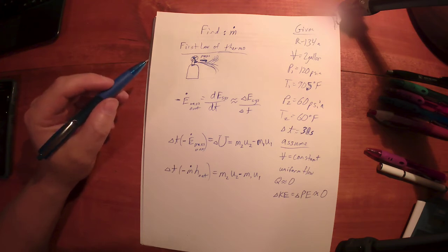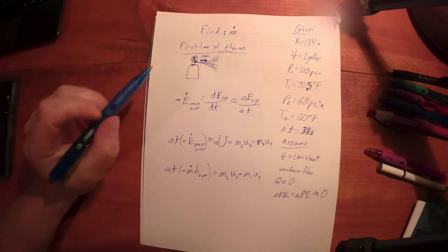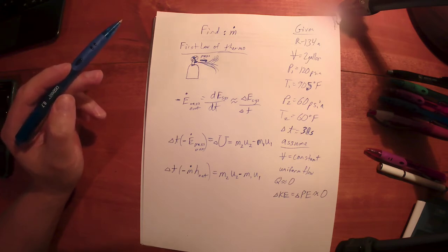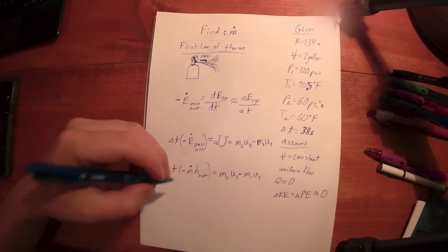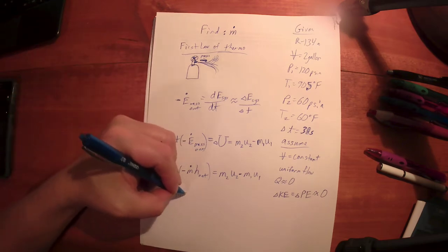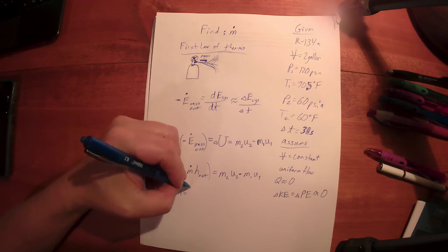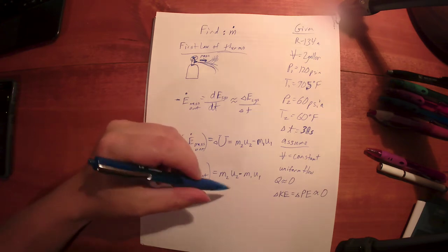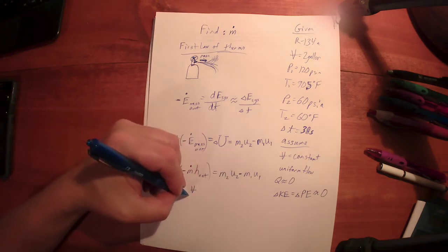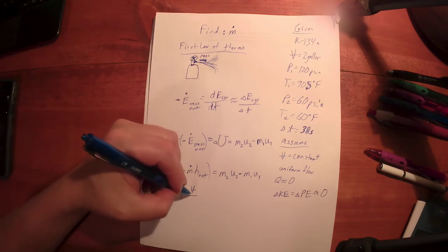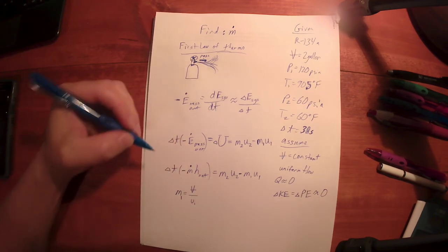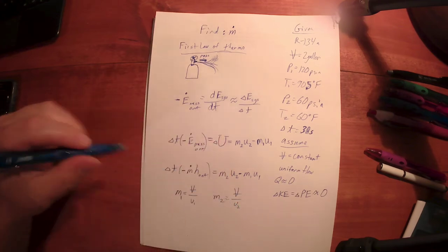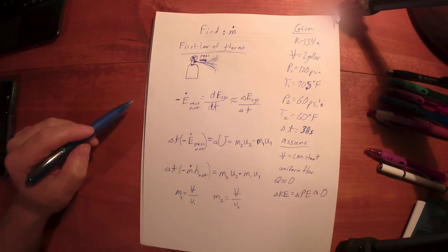Well, I would suggest here's a situation where you pause it and you go try to find a way to find the masses. Now, if you're back, how do we find the masses? Well, you find the mass based on what you know, the total volume. Now, the specific volume, if the u values change, that also means the specific volumes change. So m1 is going to be the total volume divided by the specific volume 1, and m2 is going to be the total volume divided by the specific volume at state 2, because again the mass is different at the two different states.